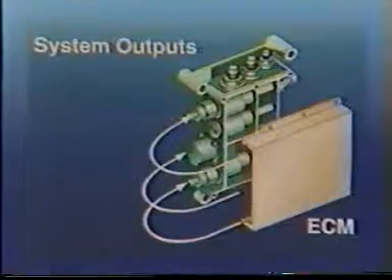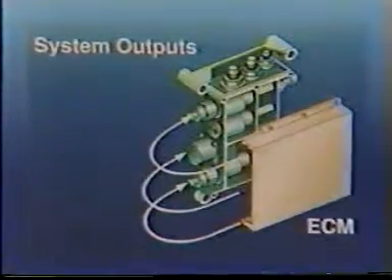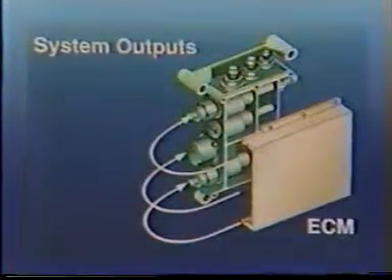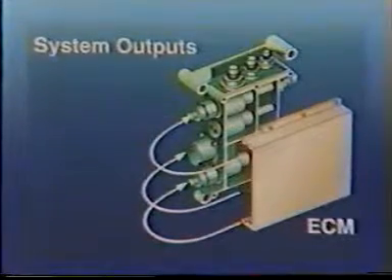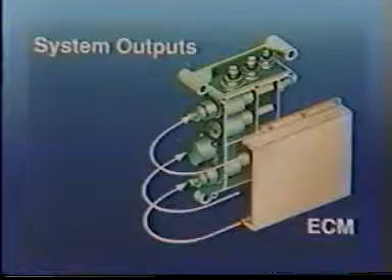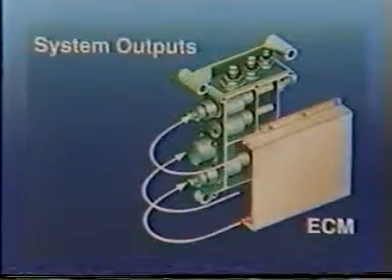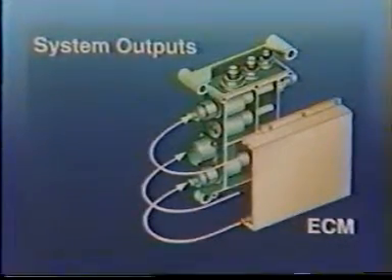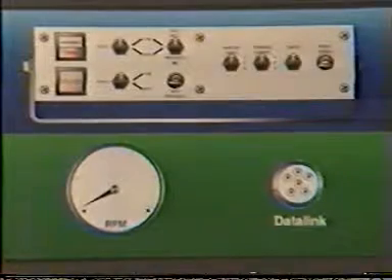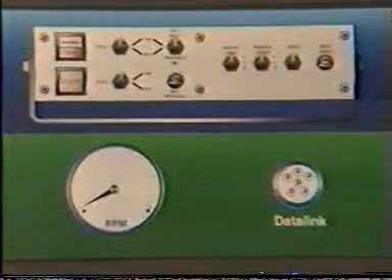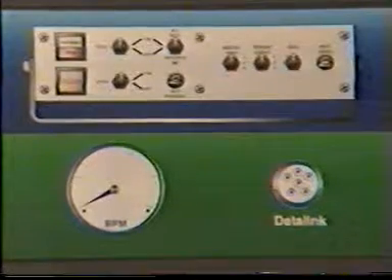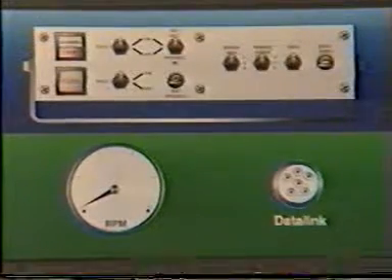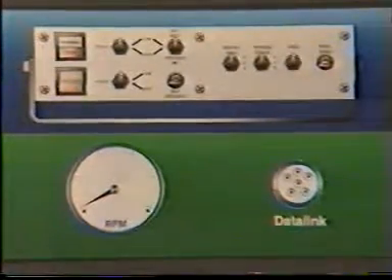The ECM produces the following signals: fuel control actuator valve signal, PWM, pulse width modulation, duty cycle; timing control actuator valve signal, PWM duty cycle; and fuel shutoff, power to the shutoff solenoid valve. The remaining 3 outputs are for system information: diagnostic lamps, fault communications, data link, system programming, tachometer, and the output signal for tachometer operation.